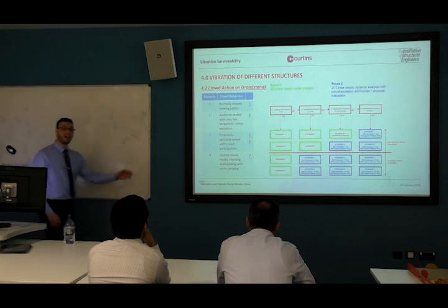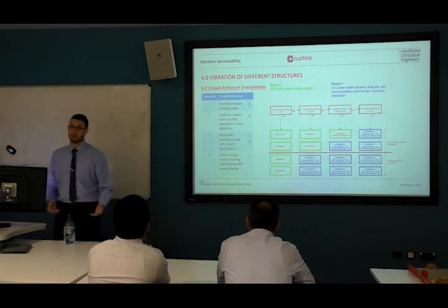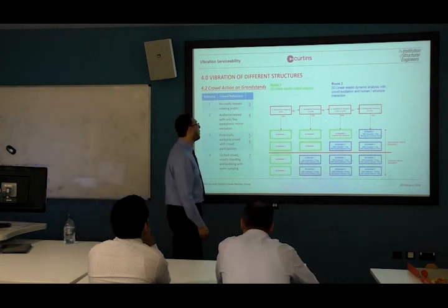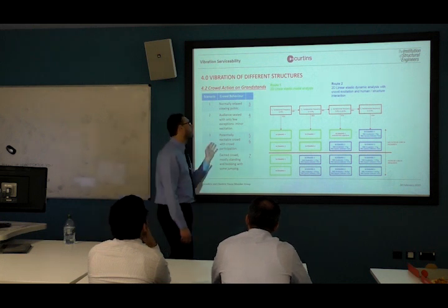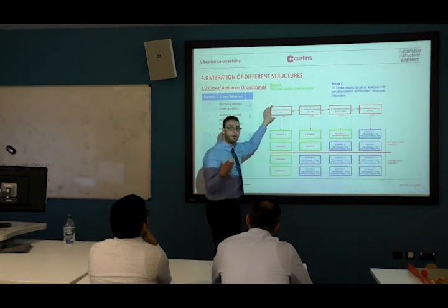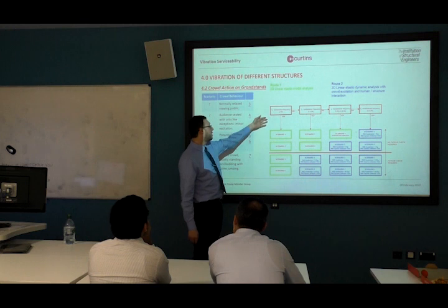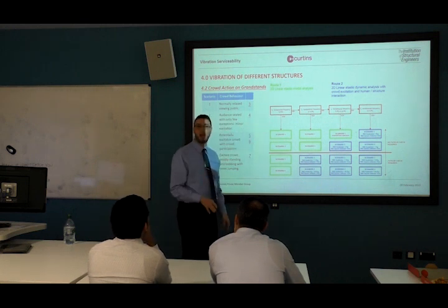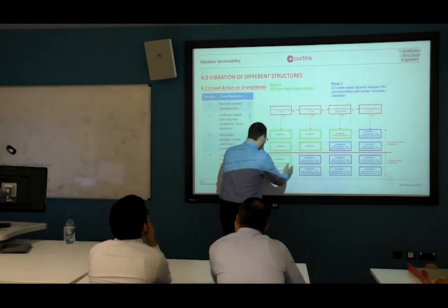Alright? So these are the scenarios that we could be finding in any grandstand. So what do we do if we have these scenarios? The IStructE guidance says, first you do mode analysis, establish your fundamental frequency. Is it greater than 6 Hz? That's fine. You don't have to do anything else. It is acceptable for all scenarios.